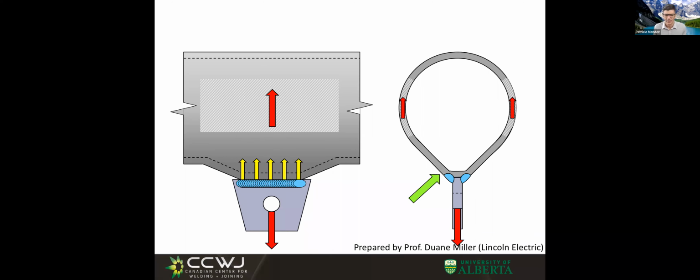But if I wanted to put this plate on bearing load on the pipe, I would end up with all kinds of problems. If it is cyclic loading, I would end up with problems of fatigue. Remember, one of the principles was, watch your toes. There you go. This toe is opening up. And Professor Miller has lots of stories about welds that went wrong by having a stress concentration in the toe in this type of loading, right? Bad design, right? That would end up having a stress concentration and having a short life.